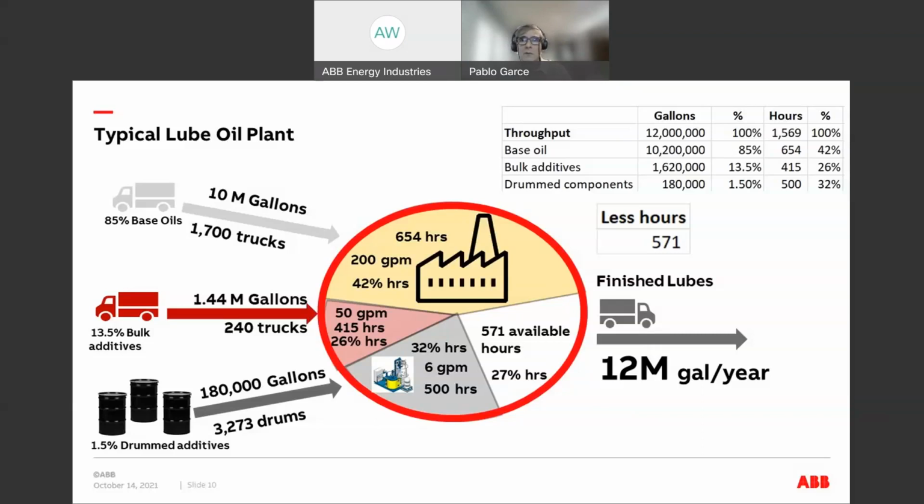If we can decant at 20,000 centistokes, suddenly I don't need to put anything in the oven. I can take it from the warehouse directly to the drum decanting machine and decant 20,000 centistokes without being concerned about the 10 hours. If tomorrow I have to use a component for a certain formulation, I have to have it in the oven the day before, because it's going to take me 10 hours to heat it up. If I forgot to put it in, then that product cannot be done today.